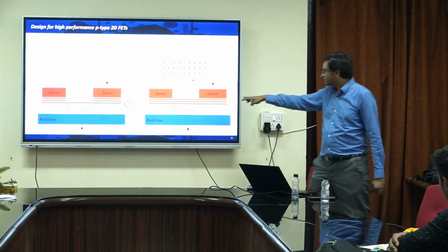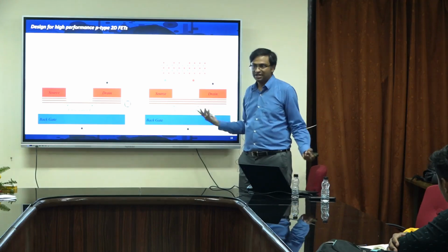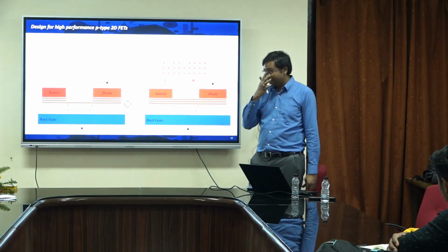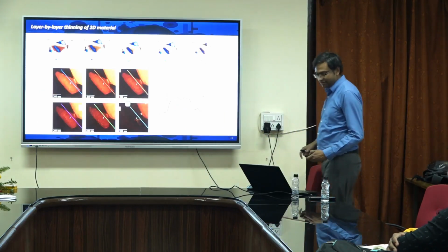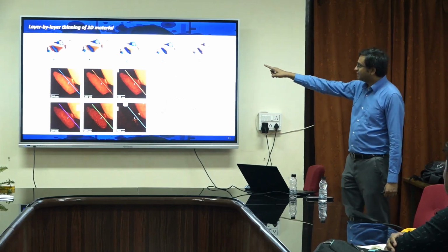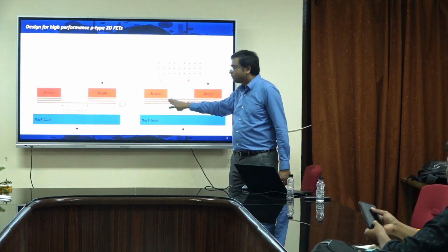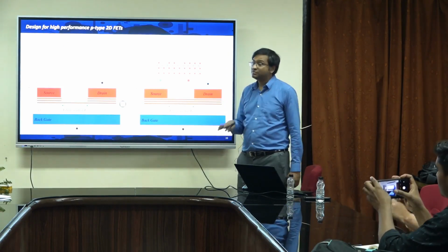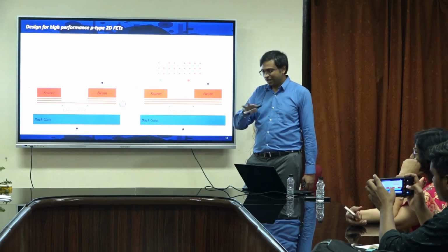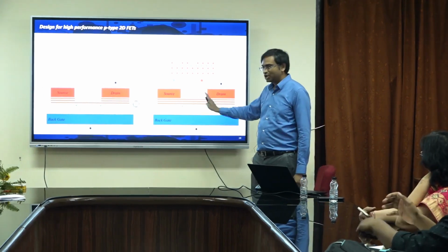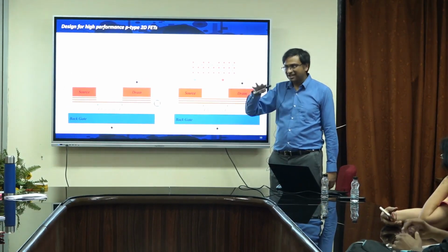It just stops over there, because the oxygen atoms cannot penetrate through, and if these layers don't see the oxygen, they cannot get oxidized. This is very different compared to a conventional 3D material. So you can actually thin it down. Here is some evidence. You take a flake and do an oxygen plasma. You convert the top layer into moly oxide, and this moly oxide is soluble in water. So you etch one layer, put it in water, one layer gone. You again put oxygen plasma, put it in water, another layer gone. This is called atomic layer etching.